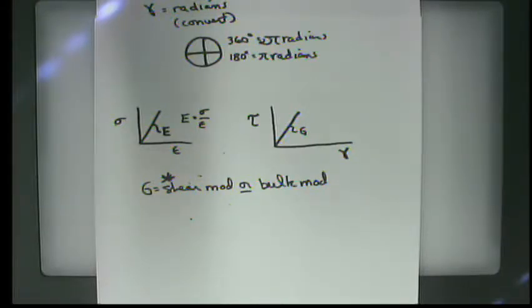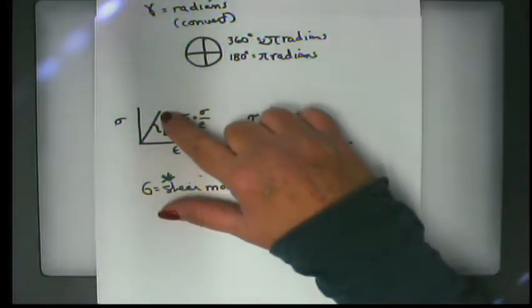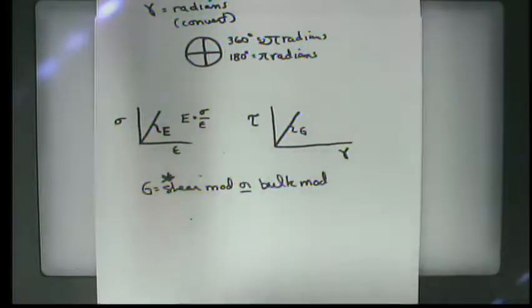That's exactly correct. And what really happens, Dane, is that after yield occurs or breakage occurs, the material becomes unpredictable because something fundamental has changed. Now, sometimes that point of change will be different. For example, if the material is subjected to repeated loading cycles, even if you stay in the elastic region, you can deform it on an atomic level or on a physical level below that number.